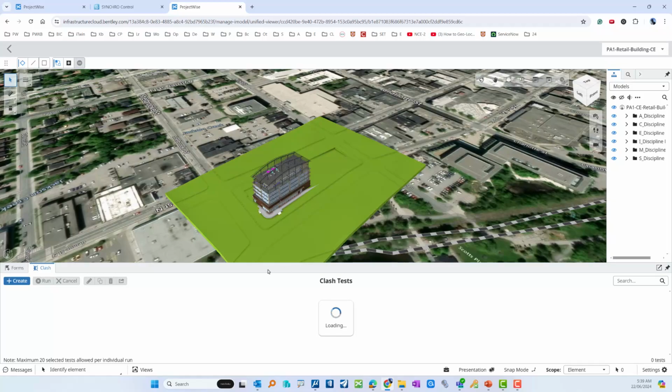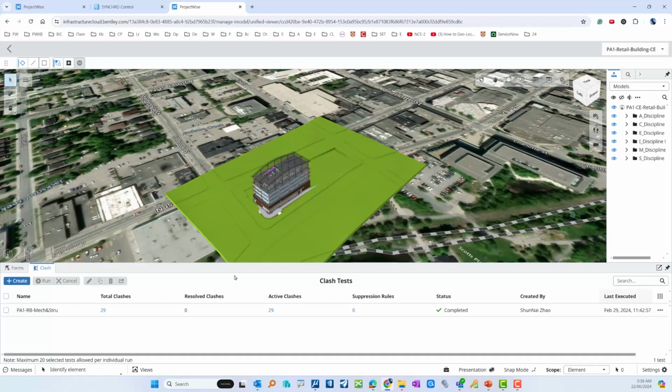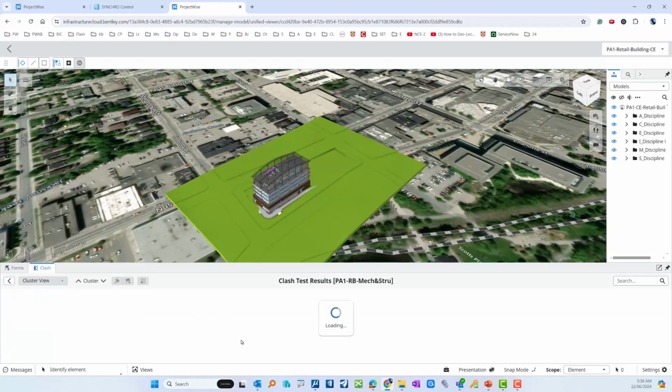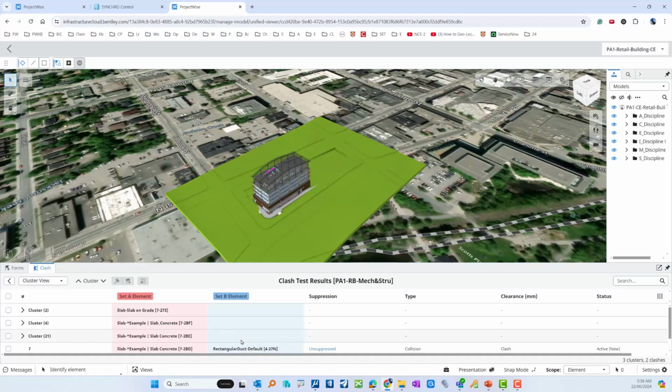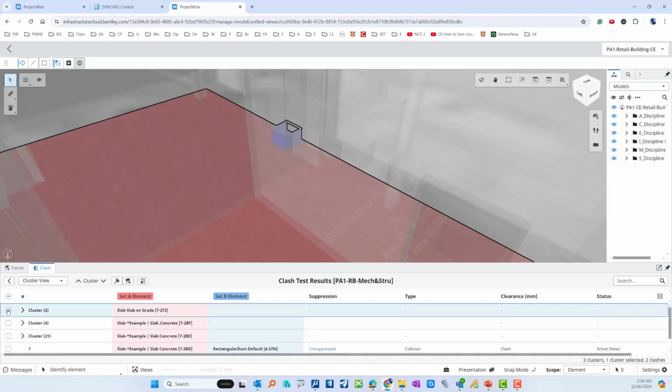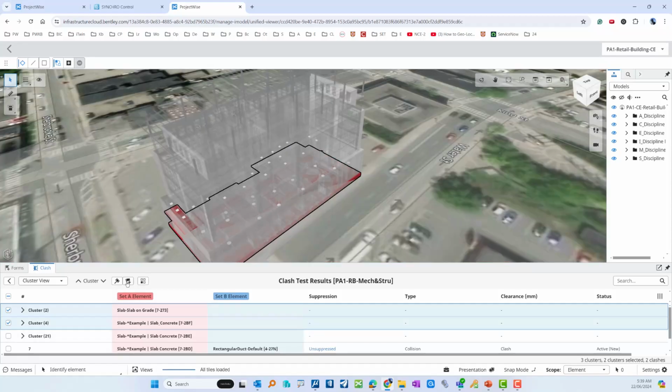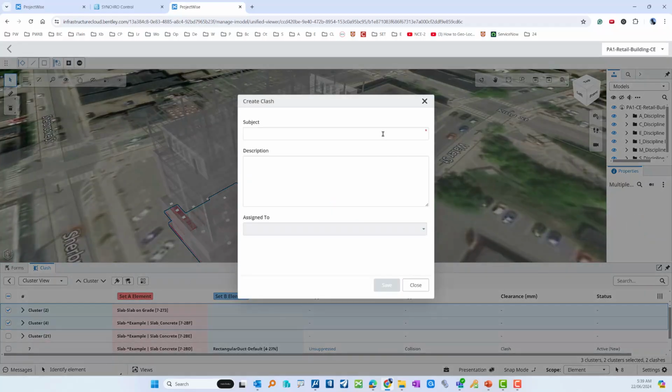After the clash detection calculation, you will get a result to show what kind of detection it is. For example, you can select a result, then raise the issue. You also found that in this situation, clash detection is using form services, right? To add a comment, to assign to someone, to associate it with some kind of workflow.